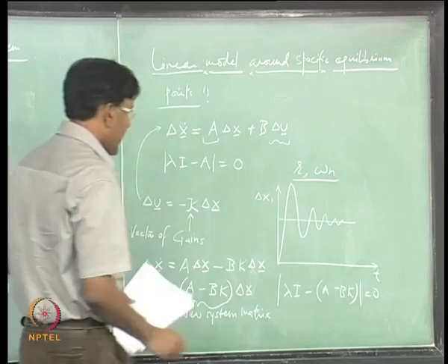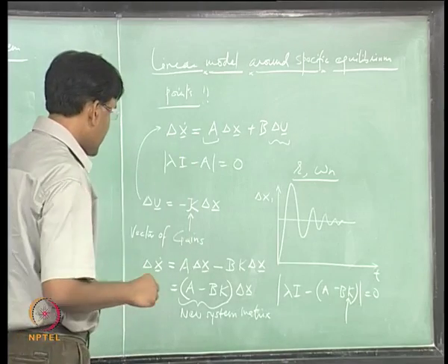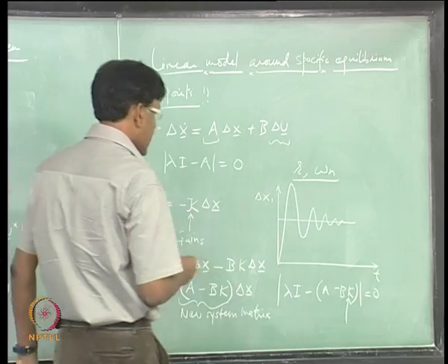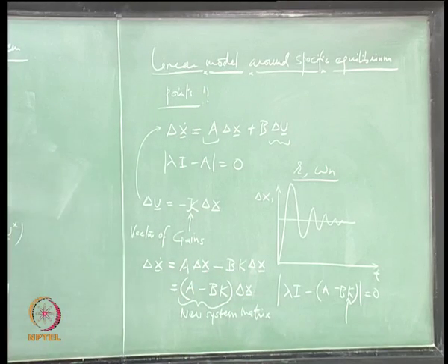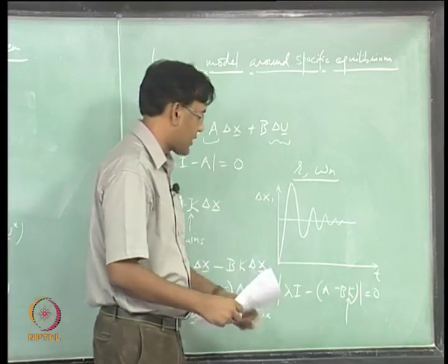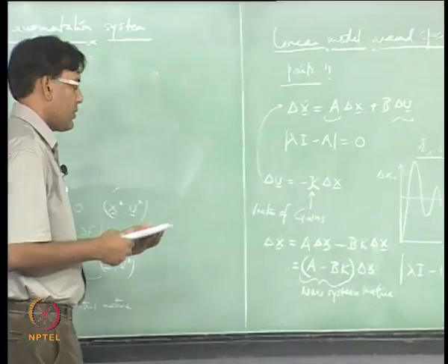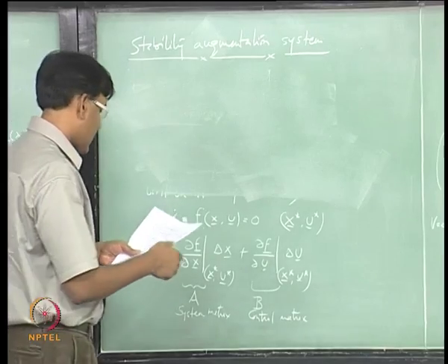So, clearly the inclusion of this matrix or the vector of gains K modifies the eigenvalues. When you change the gains, it moves the eigenvalues to a location which is desired, and that value of the vector of gains can be used to design the feedback control laws.